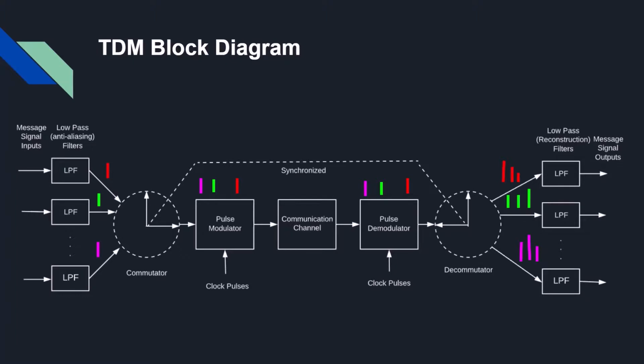Multiple samples of each signal will come and we will process them through a low pass filter and then we can extract our signals. So this is how multiple signals share the same medium for communication. We have completed time division multiplexing.